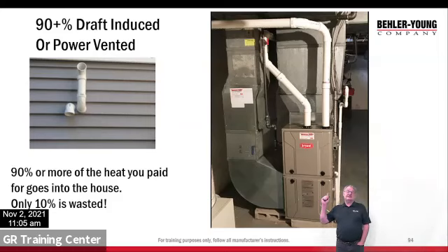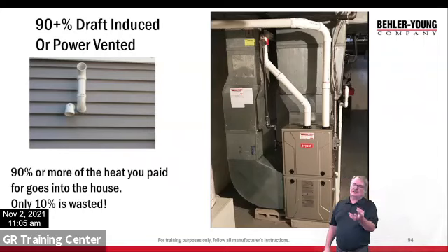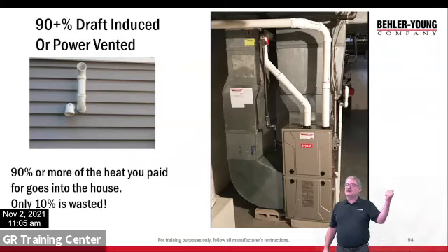Second thing, I see two pipes. And on the outside there, I see two pipes because all that combustion air, remember that 1,500 cubic feet of combustion air I needed that I would have used to draw from this basement? It's coming from outside now. So now I'm not going to take all this heated building air and throw it in my chimney. I want to bring the air in from outside. So all the combustion air, any dilution air, which I really don't need anymore, is all coming from outside.